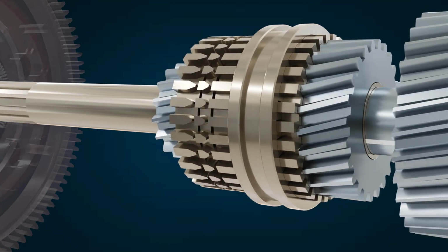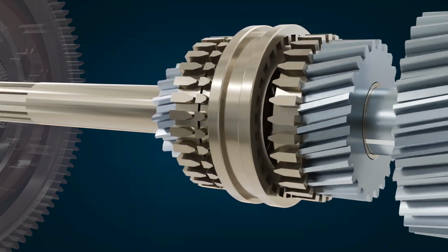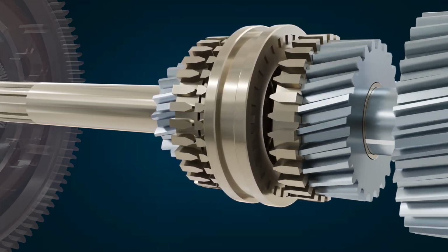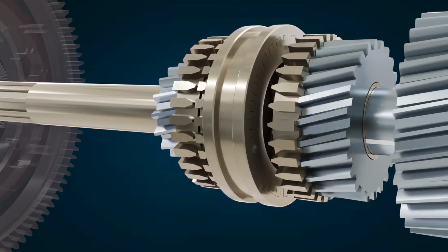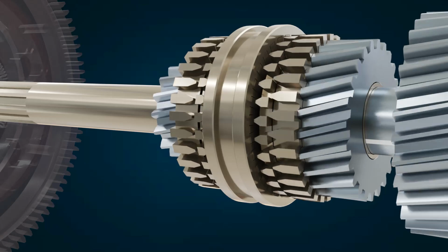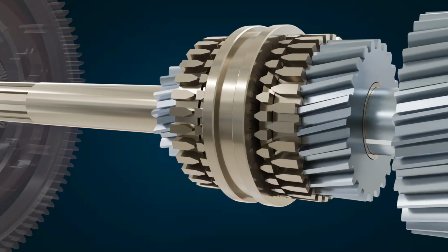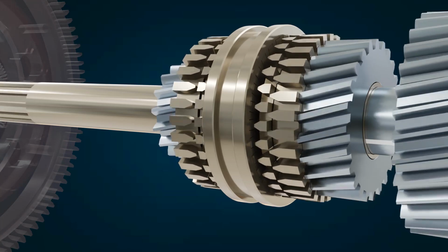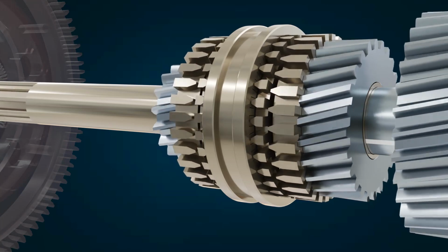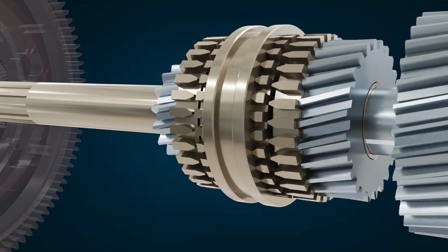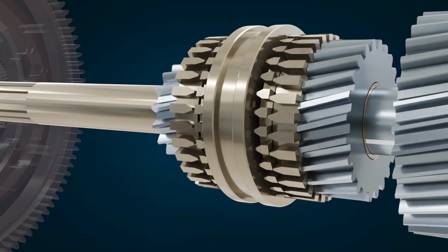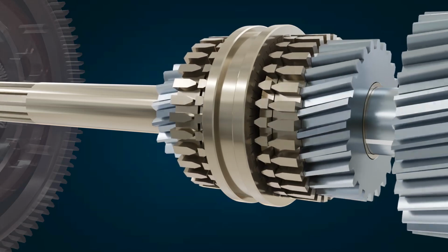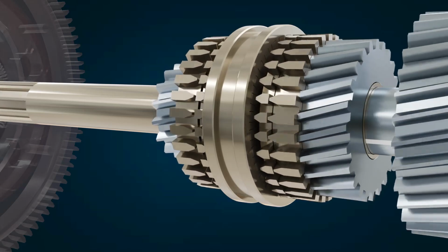But during the gearbox operation, the shaft and gear will be rotating at different speeds, so such a locking action is not an easy task. A synchronizer ring helps to match the speed of the gear with that of the shaft. The synchronizer ring can rotate along with the hub as well as slide axially. Before moving the sleeve, the clutch pedal is pressed this way, and power flow to the gear is discontinued.